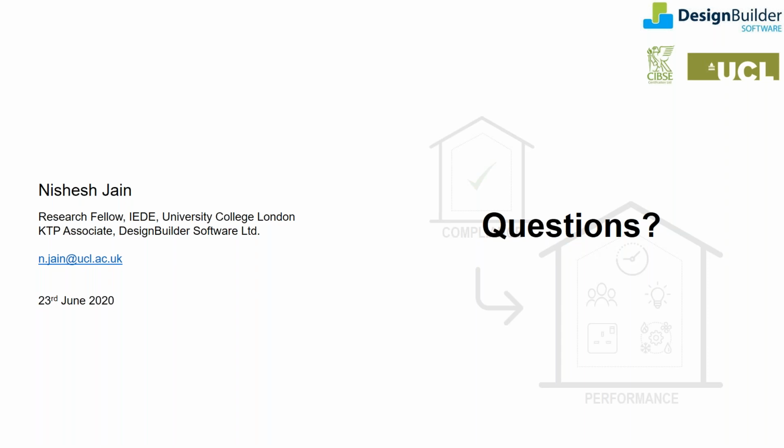So basically, sensitivity and uncertainty analysis is a key component. The reason you are doing performance modeling is you want to estimate as realistically as possible what your energy projections would be. As every modeling does, it includes lots of assumptions, and therefore you're not very sure that what you put as inputs is actually going to translate in the actual building. As TM54 suggests, you can have discussions with the designers and with the stakeholders, the intended occupants or building managers, and take them on board on how you intend them to run the building.